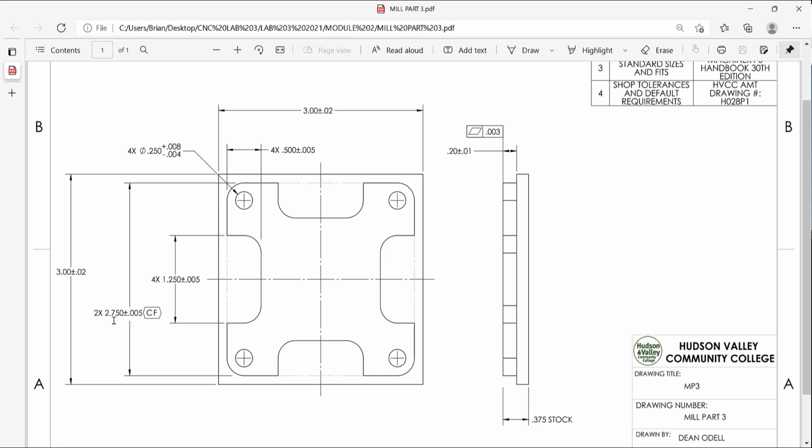And again, it's not going to match the drawing nicely, but I think it's just a cleaner setup to do it this way. We could do a midline and tolerance the midline and then tolerance the width. But the problem is, what are the tolerances at that point? Because let's say it shifted this way 3 thousandths, and the size is a little bit smaller. How do you relay that to somebody?